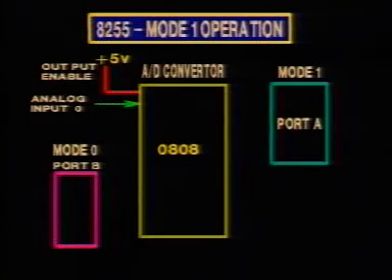Therefore, the data transfer between the A to D converter and the CPU not only involves the digital data but also the start conversion and the end of conversion. Therefore, a mode 1 operation is called for. In addition, certain A to D converters require address information to select one of the many channels that are available. This calls for operation in mode 0. Now let us move on to the graphics to interface the A to D converter 0808.